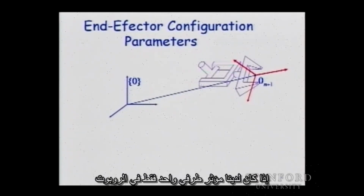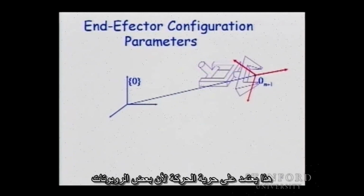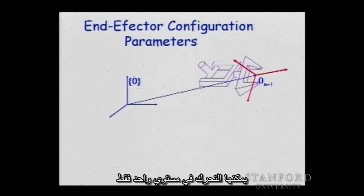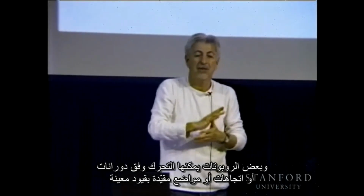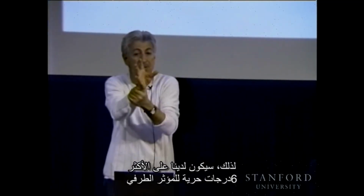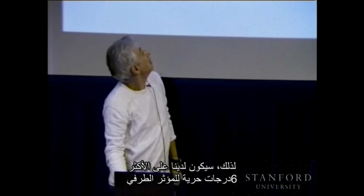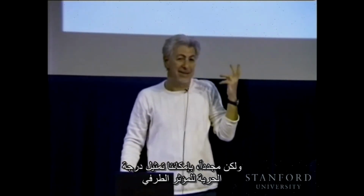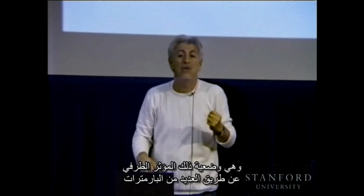So if we have just one end effector in the robot, essentially we have just one rigid body. At most we need, depending on the freedom, because some robots can only move in the plane, some robots can move with restricted rotations or orientations or positions. So at most we are going to have 6 degrees of freedom for the end effector. But again, we can represent that freedom of the end effector, that is the configuration of the end effector, with many different